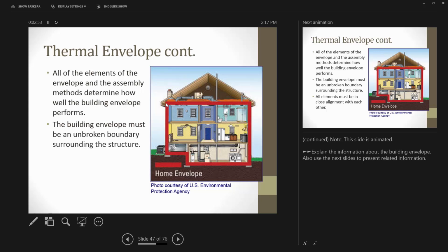And if you start to have pathways in there where you have to start moving and taking a lot of 90s and jigs and jogs and all the different angles, it usually creates, when you've got connections and corners and direction changes, potential problems and interruptions in the thermal envelope. So we'll talk more about design. We're going to play with some different wall assemblies when we do our res check, and we're going to start to change assemblies to see how one assembly performs better than the other.